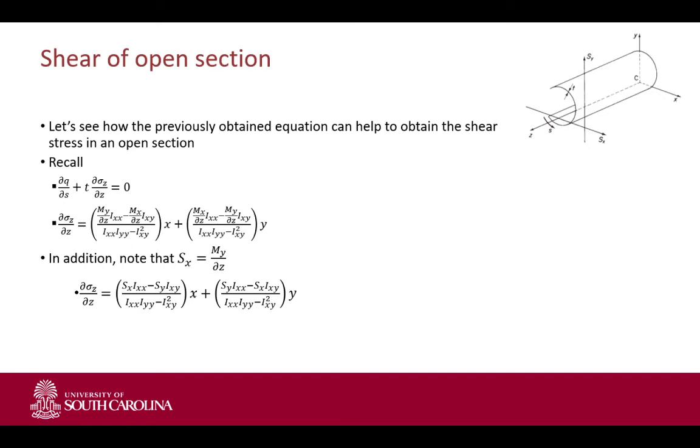So noticing that the shear force in X is the variation of the moment in Y with respect to Z, we could substitute that back, and now we have our direct stresses as a function of our applied shear forces, Sy and Sx.